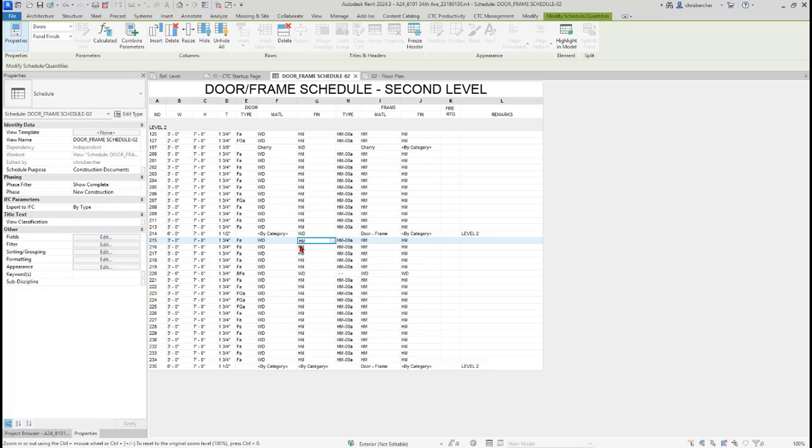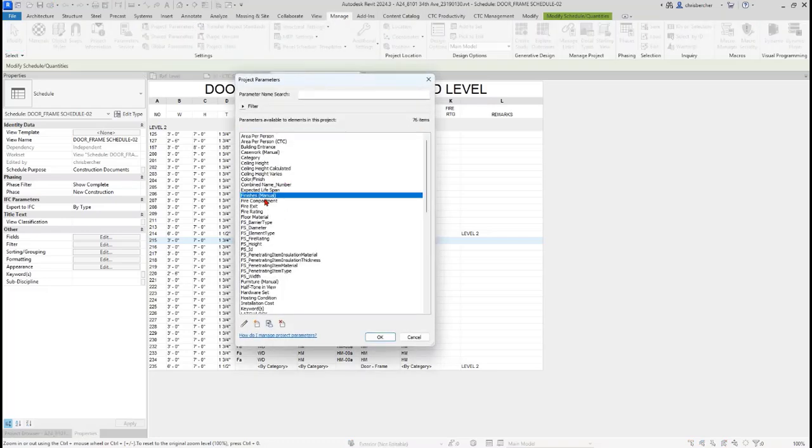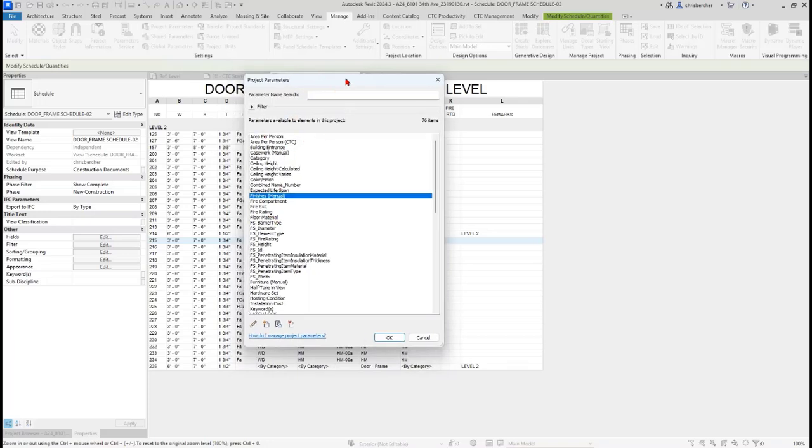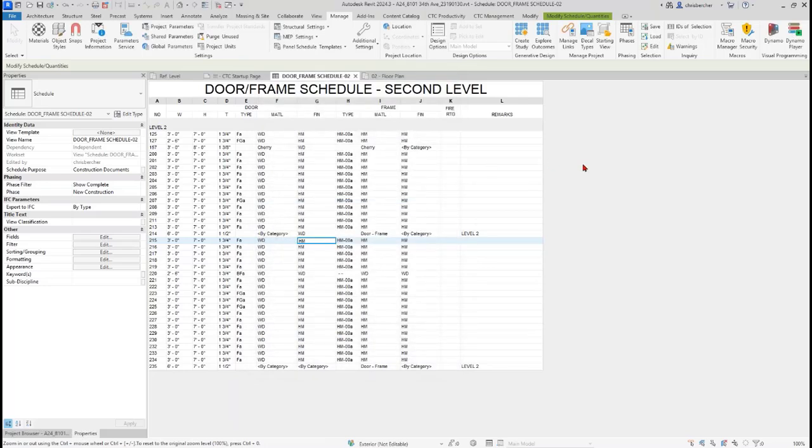There's one thing about this process that I want to point out: in the project parameters list, panel finish and frame finish don't exist, or appear in schedule. They're not in this list. So our tool is not just adding project parameters and adding it to the schedule. That's not what we're doing. Because they were already in the project that came with the other families, we are basically editing the family and adding the parameter to the family, right? And in some cases, doing the swap. So you don't have to worry about anything extra coming along for the ride.